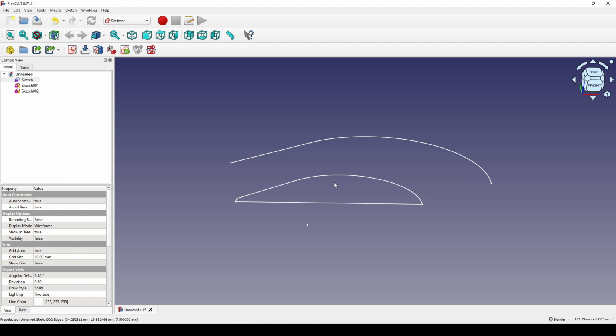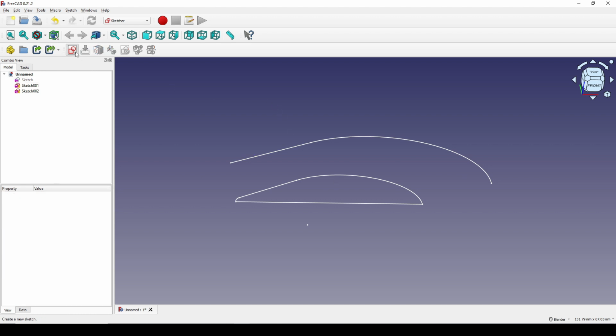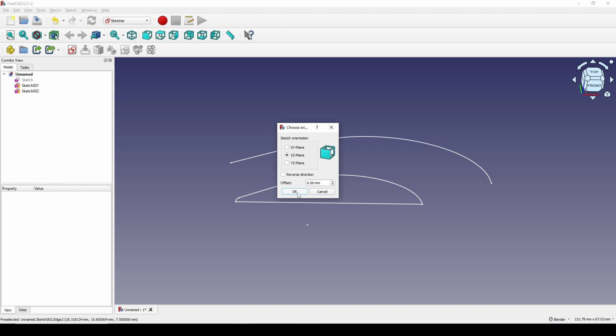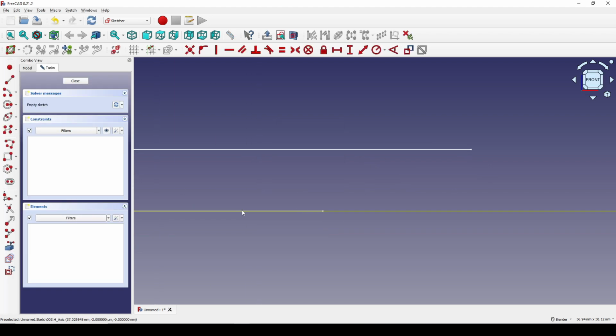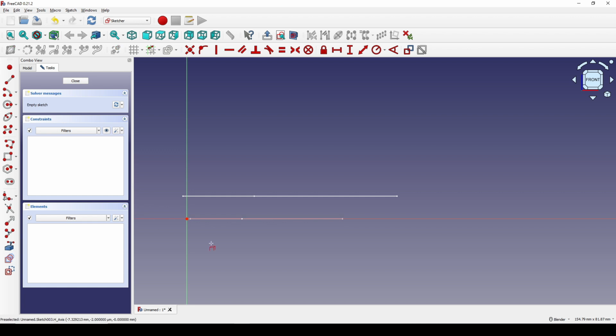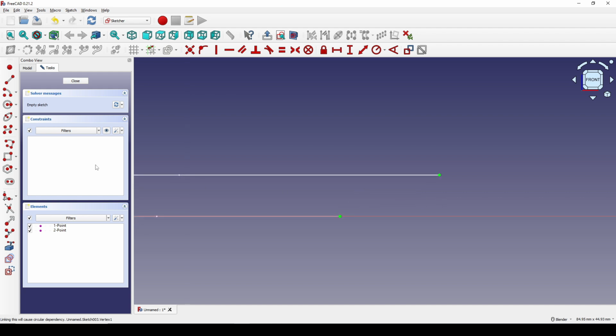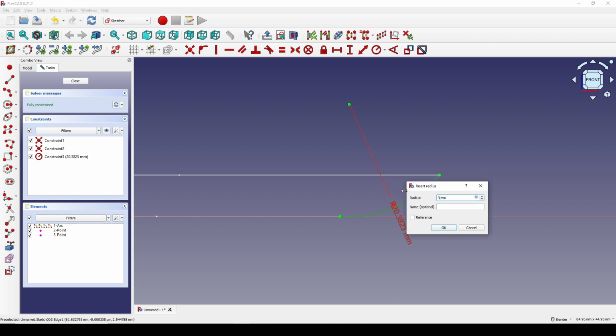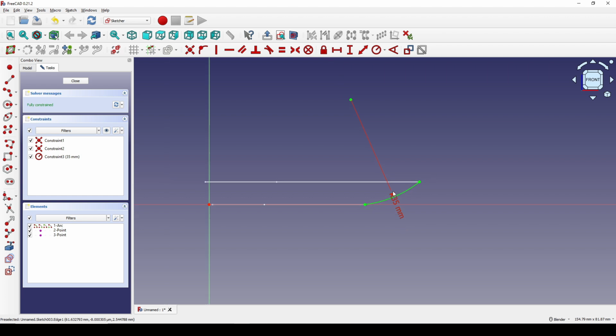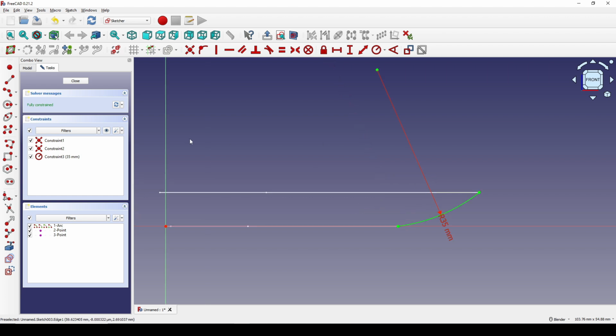Hide. Next, I will create another step on the front view. And I will reference this point and this point. I create an arc in between, a 3-point arc. And I select this arc, hit R and 35. I set the radius to 35. Next, I close the sketch.